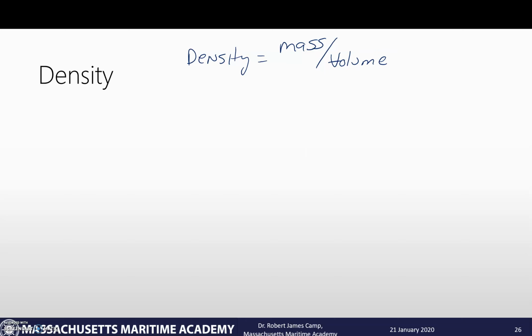Density is highly variable in gas, and it's almost proportional to its pressure. Density is nearly constant in liquid. We typically treat liquids as incompressible. That's not necessarily true, but it's close enough. If you look at water, it takes about 220 times the pressure of the atmosphere to compress water 1%, but we still say, okay, it's generally incompressible because it's really hard to compress.